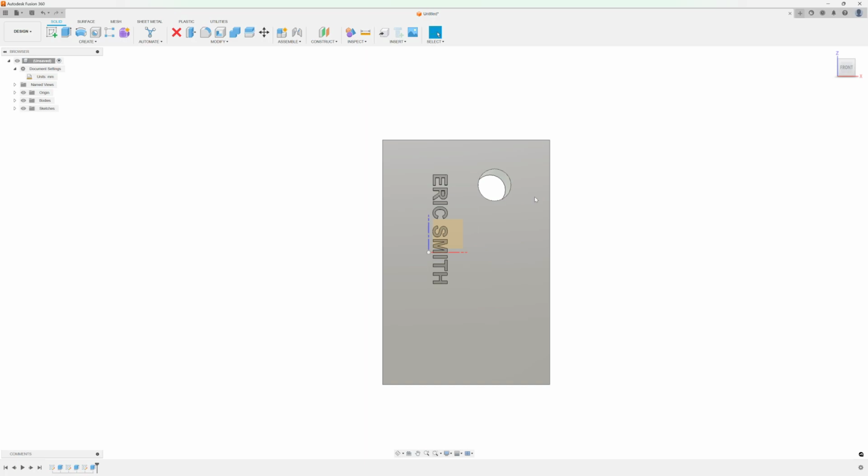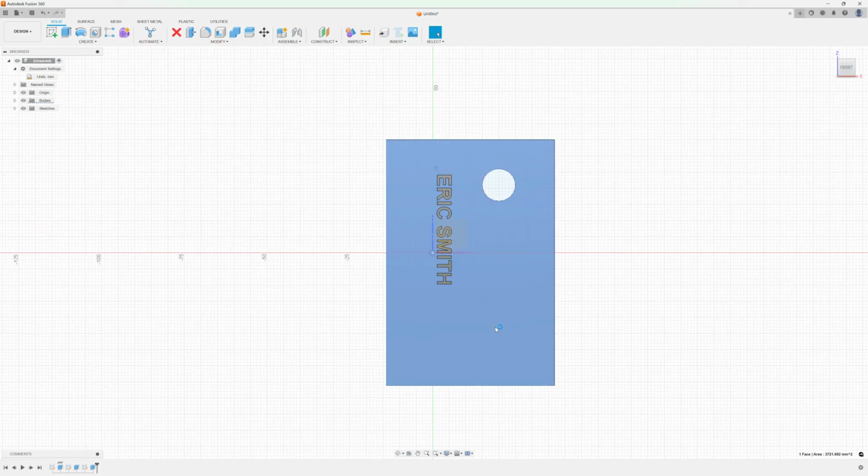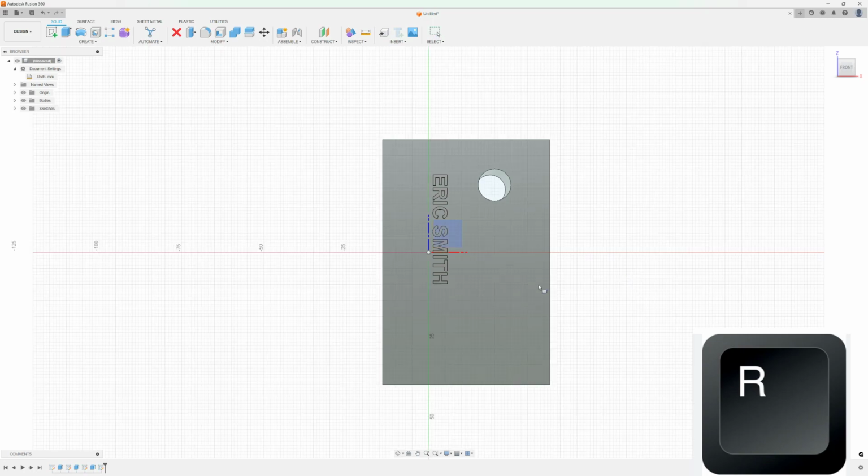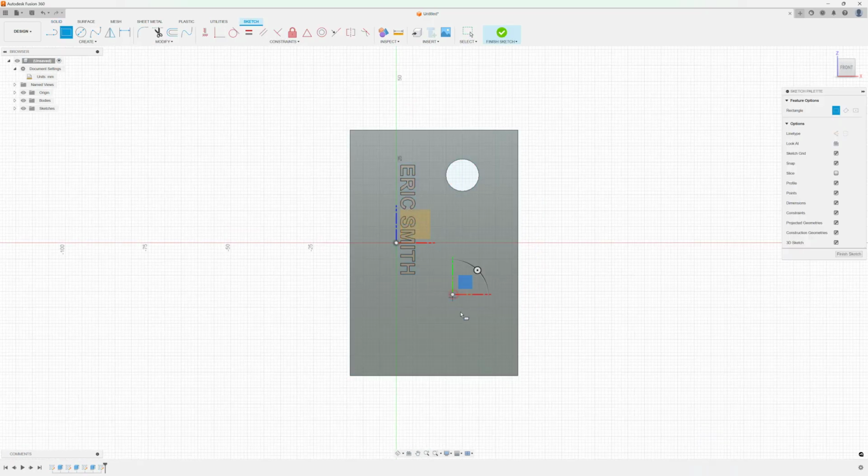And anytime you want to get specific with stuff, everything is really easy to do. If I want to make another hole here, maybe I want to make a rectangle hole. So I'll hit the R. Let me click finish. I'll hit the R key, and I'll click on the front here, and I'll make a little rectangle. As you can see, you got your 19 and 9 here. Maybe I want to make these certain sizes. You can hit your D key.